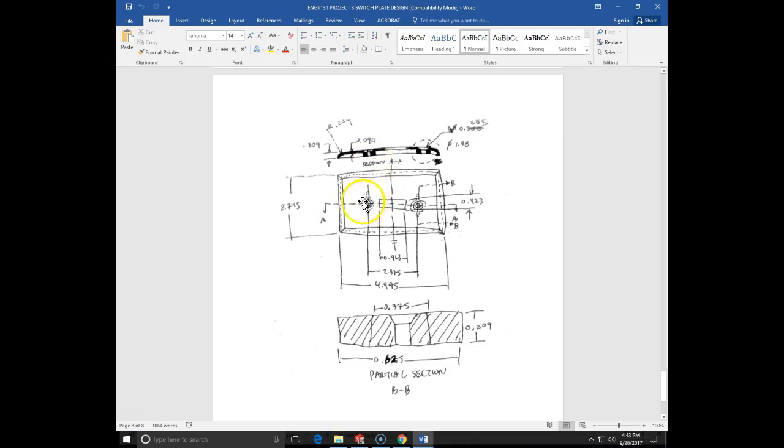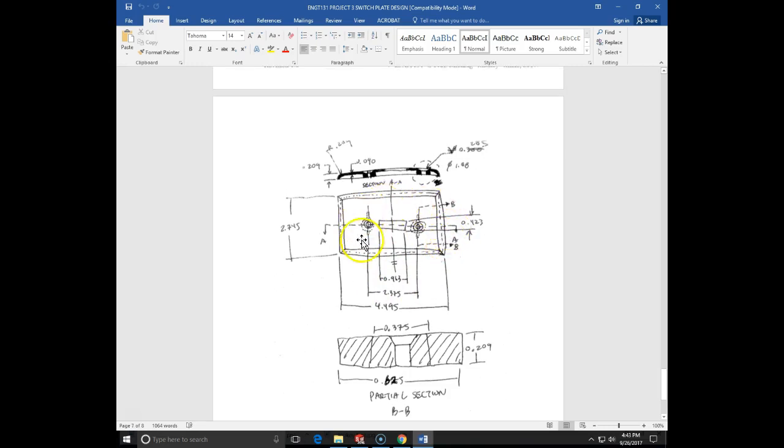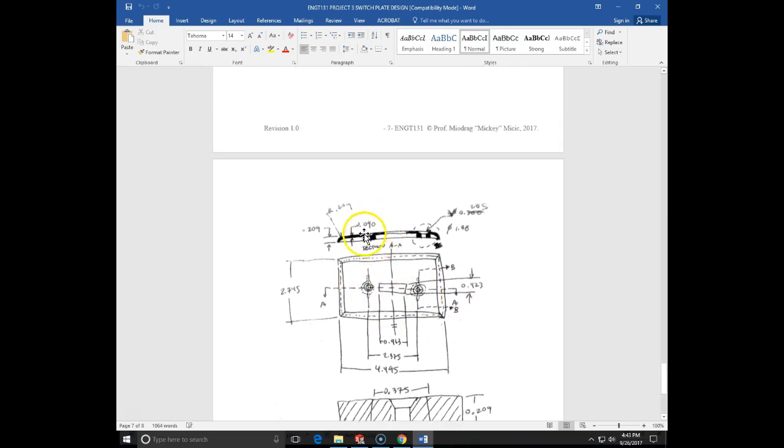So just use the standard number 6 countersunk through hole. This is the standard dimension. Your switch plate may be of different dimensions, however, the size of the cut for the switch and the positions and relative size of the screws to mount the switch can't change. Also, be aware that the switch plates need to be hollowed from inside, otherwise the switch will not fit.